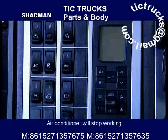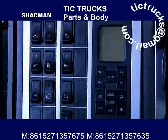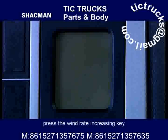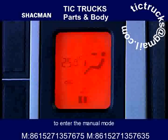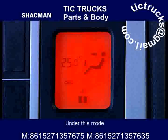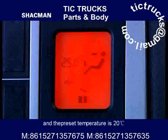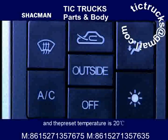Off key. 1. When the air conditioner is on, press off to turn it off and close the LCD. The air conditioner will stop working. 2. When the air conditioner is off, press the wind rate increasing key to enter the manual mode. Under this mode, the wind rate will be set at step 1 and the preset temperature is 20 degrees centigrade.